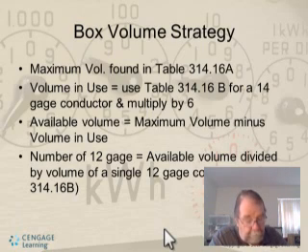So what we do is we take the 14 gauge conductors. They're 2 cubic inches, and you multiply those by the 6 of those, that's 12 cubic inches. You subtract that from your 30.3. I'm going to forget the .3 for right now, and so that leaves us 18.